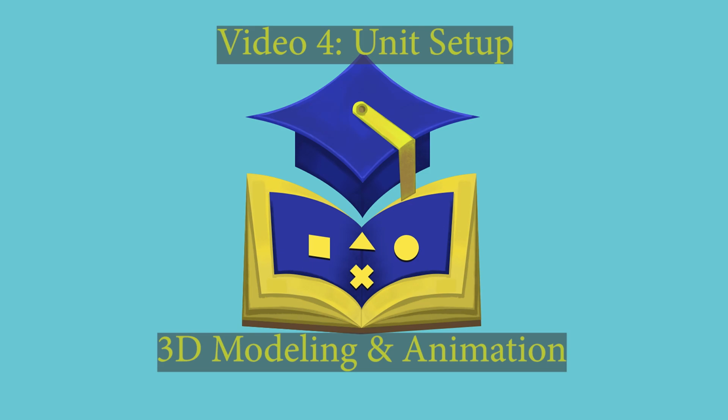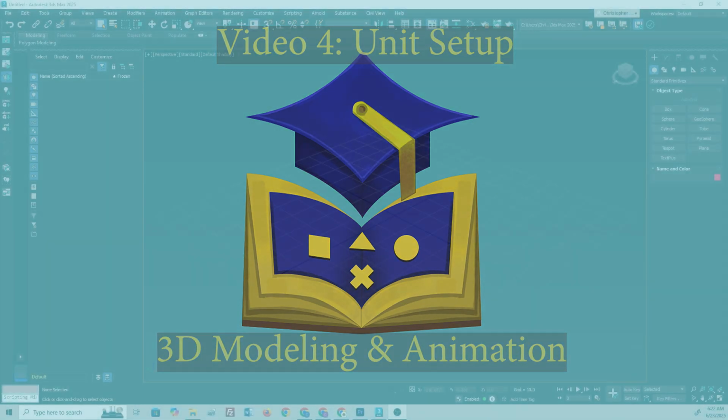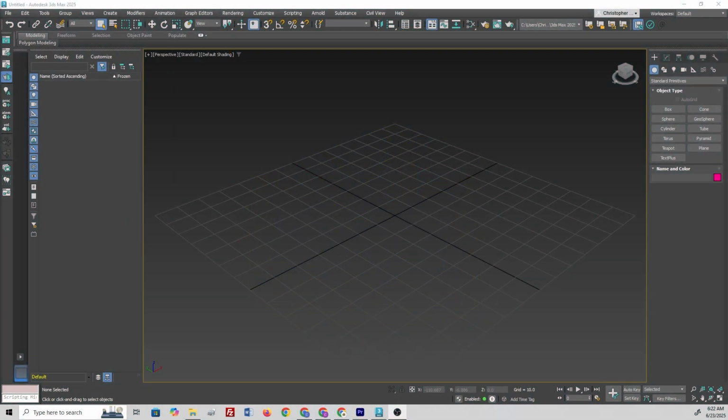Before we start building anything serious in 3ds Max, like furniture, buildings, or even characters, we need to make sure that the units we're using match real-world measurements. Think about it like this. If you're modeling a chair and don't set your units right, 3ds Max might think it's the size of a mountain, or a paperclip. That's why setting up your measurement system correctly is critical, especially when you're designing something that's meant to be a certain size.